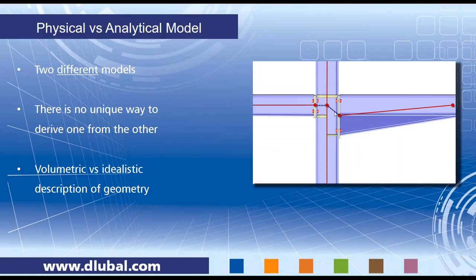So some software has eccentric links that can be used, and they don't actually need a separate member to connect those gaps here. Or in a simplified model, we can just ignore this eccentric haunch here and just have a straight member. So there are different ways we can do it, and obviously it needs a little bit of the help of the engineer to decide how they want to build that model.